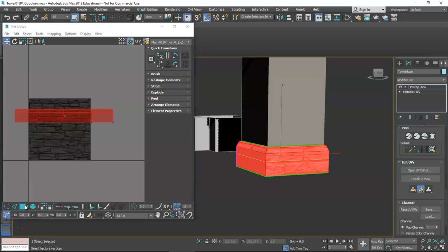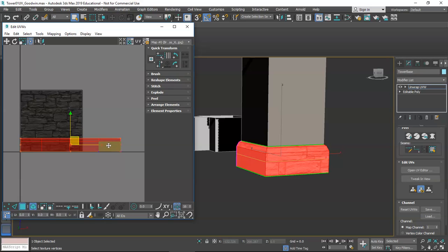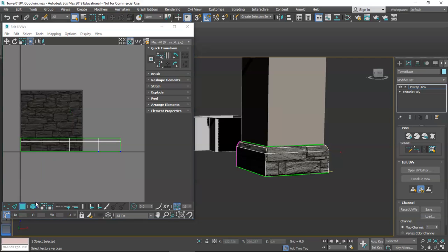And then I can go into polygon mode and turn on element mode just in case. We'll click and drag this. Then I'm going to get my freeform, and I'm going to hold Control, and that'll keep it somewhat seamless here to pull up. We got some wonkiness there. Turn this element mode off. This is uneven compared to this one and this one.